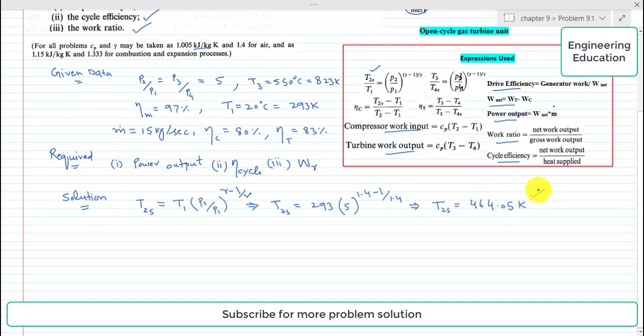Now from the definition of the isentropic efficiency of the compressor, we know that the isentropic efficiency of the compressor is equal to T2S minus T1 over T2 minus T1. In this case we have T2 which is unknown. So using this expression we will find the value of T2.